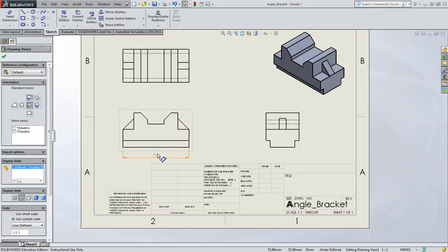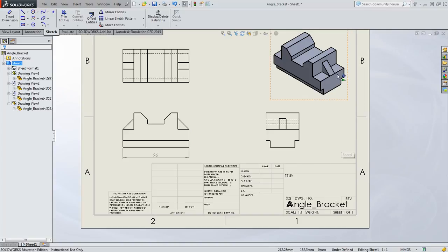If we can avoid it, we try not to put dimensions in what they call the gutter around the border of the title block. We can have it inside. It would be ideal. As I said, I don't practice or rehearse these drawings. I'm just shooting off the cuff. So I wanted to document the proper process of going through this, even if I make mistakes. I want you to see how I think so you can start to think like me.